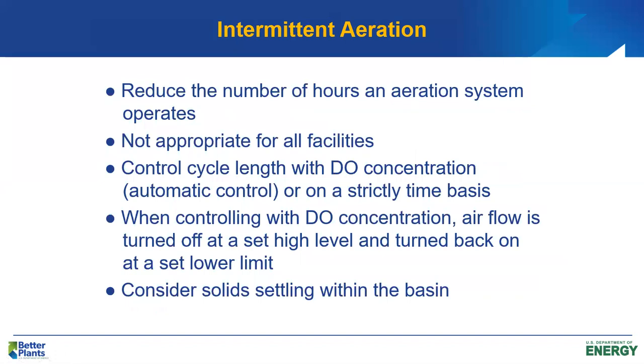Intermittent aeration, turning aerators on and off, may not be appropriate for all facilities, but in extended aeration facilities where we're nitrifying, we have a lot of nitrates, we can save energy by turning off the aerators a few hours a day without adversely affecting the performance of the activated sludge process. And then installing a DO control system so that the speed of the aerators may be controlled, or we'll turn aerators on and off depending upon the set point DO concentration in the mixed liquor.